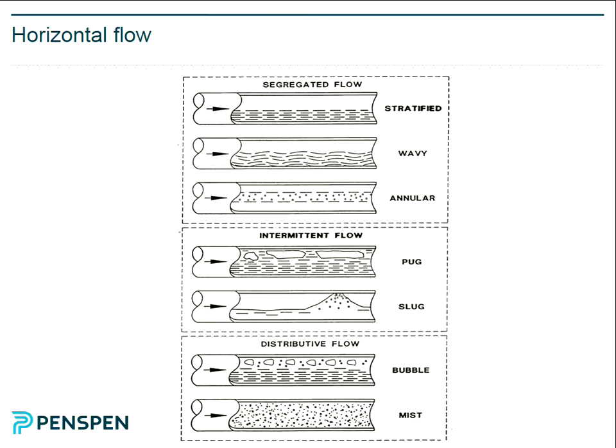So these are examples of vertical flow. Bubbles, a bit like a pint of Guinness. The bubbles going up, being transported with your product. Imagine in a well, you're just producing from a reservoir. You've just gone below the bubble point. You're getting bubbles just starting to form in the matrix of oil. You get this type of flow. Basically, it's two-phase flow. It's relatively efficient.